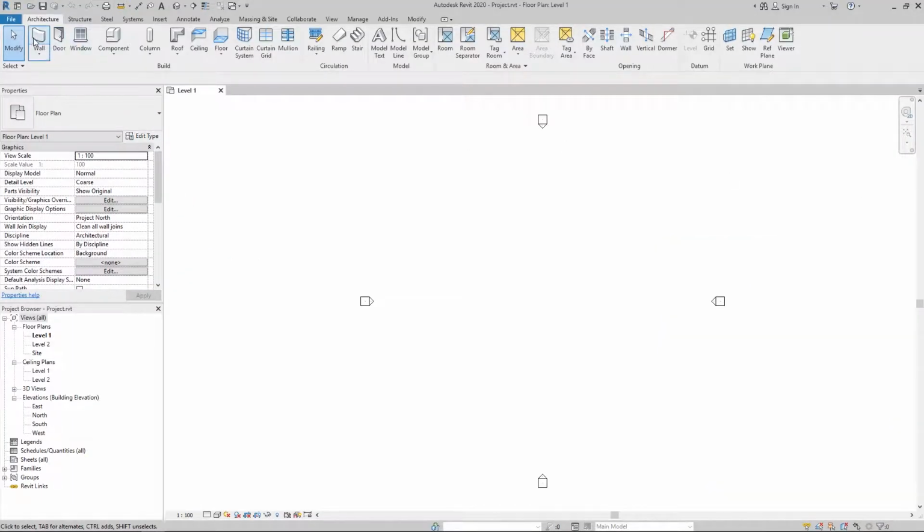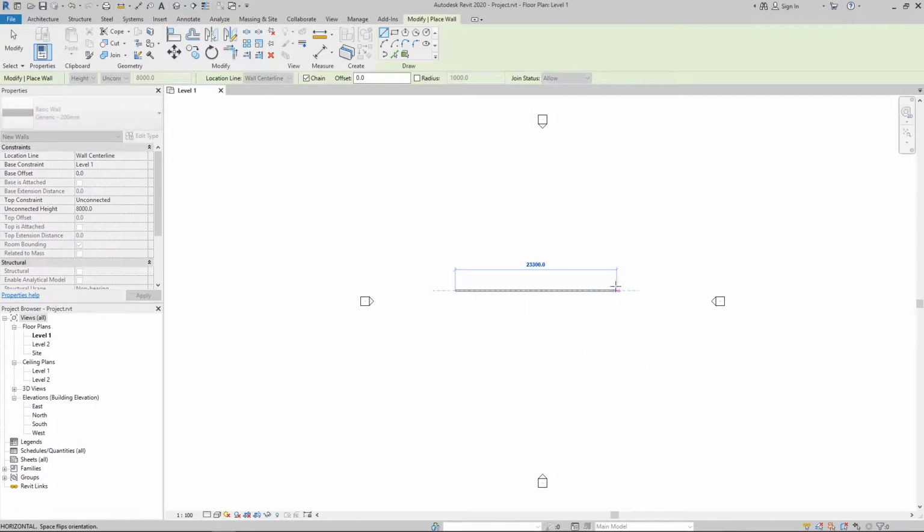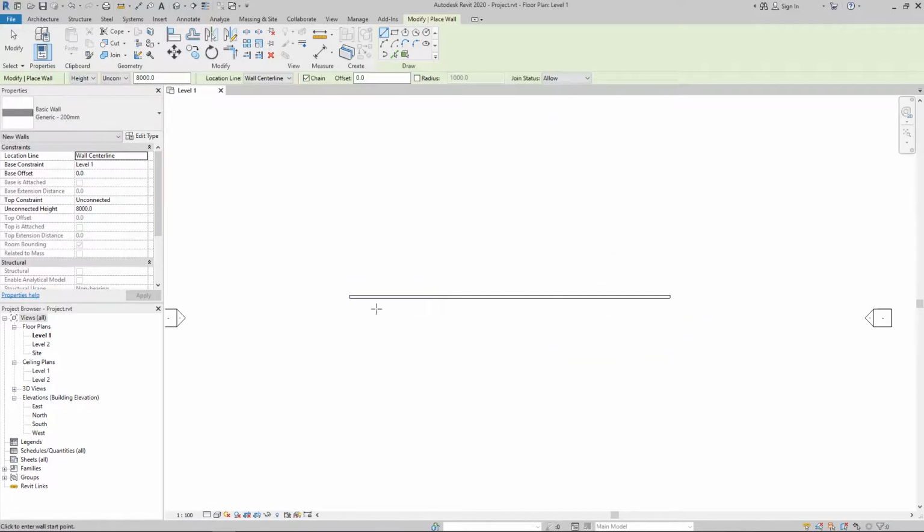First, we are going to talk about the creation of walls. I just click here and we can create here. Just click and click. Here in the options bar we can see some basic parameters. Here we can define if we are creating this wall from its height or its depth. It means that from the level that we're creating, in this case level 1, height is going to go up, and depth is going to go down.